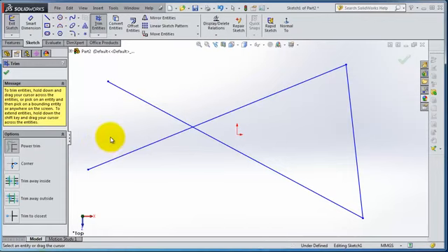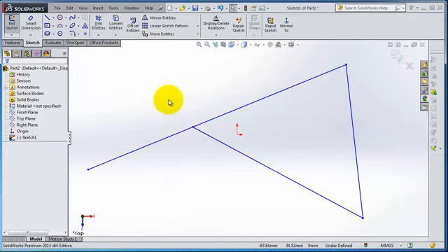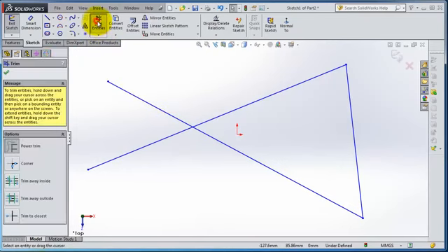So to use the power trim, just keep holding the left mouse button and make a line. So you are trimming, and again holding the left mouse button, move, then you are trimming. Control C. Let's activate trim. We have power trim. You can also trim both of them at once by clicking or drawing that trimming line.